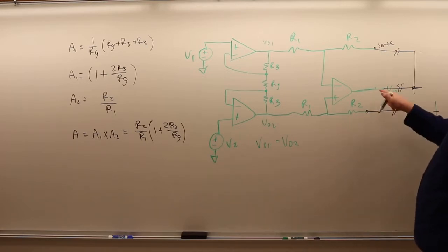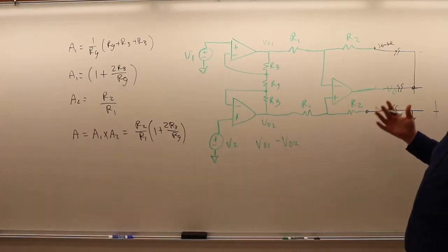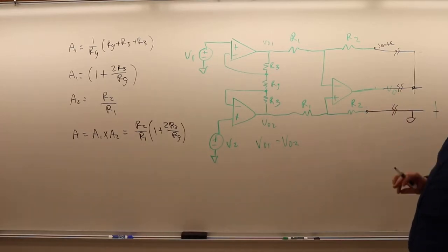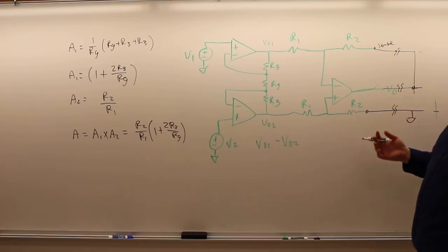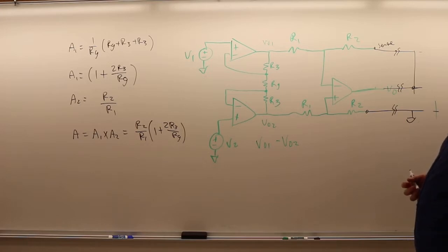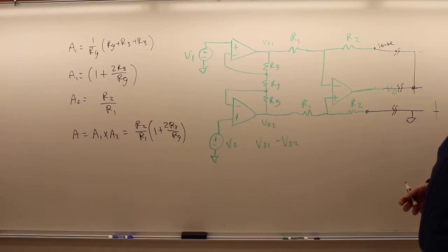So it's a way to guarantee that the output voltage actually at the destination is correct. Because sometimes even if your output voltage coming out of your chip is correct, that doesn't mean it was correct all the way at its destination. This is one way that you can help improve that. You can help clean up any noise or any parasitic resistive effects that might have been created by having that long distance movement of an analog signal.